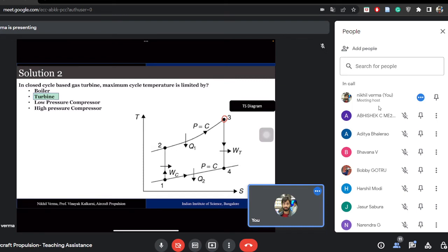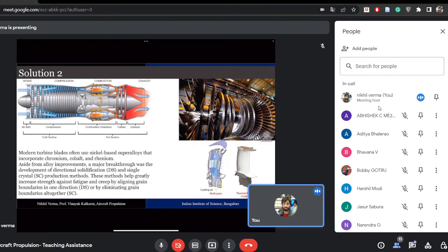After the combustion chamber exit, the turbines are rotating at a high RPM, which results in an axial load on the turbine blading. The axial load, the heat transfer and the metallurgical limit restrict the turbine inlet temperature. In modern gas turbines, nickel-based alloys are used to make the turbine blades.